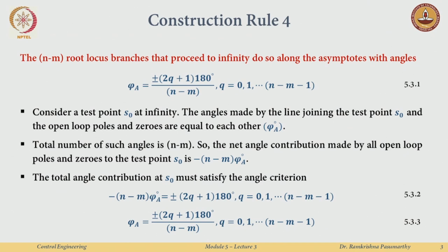the next step here is how the root locus branches go to infinity. For example, in the motivating example we had the poles at 0 and minus a, and they meet here and go to infinity. Now, what decides this? Why don't they go something like this, or like this? Or why don't they, instead of going on a straight line, just follow a lazy path and go a little more adventurous this way? So who decides how they go?